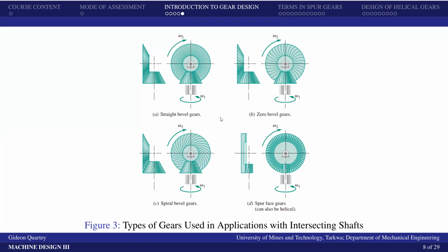The various bevel gears we have looked at are conical in shape, but this particular one is not. It is just like a disc. The other one, which is the pinion, is in the form of a spur gear, with gear teeth round the wheel of the gear.